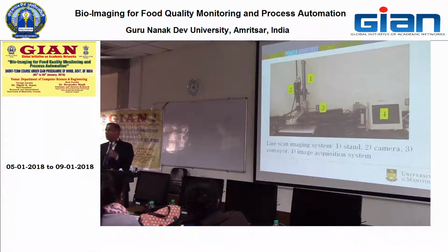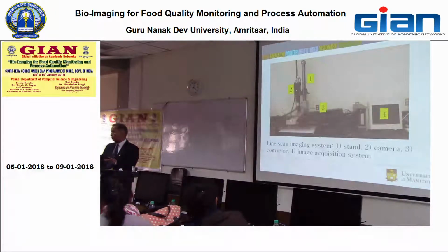By putting the lines together you make your 2-dimensional image and extract the information. You can also use the area scan camera for automation, but you have to design the movement so that there is not too much overlap on the image. Otherwise, you would be confusing the objects. As long as the gap between images is such that they don't overlap, you can use an area scan camera to take pictures of moving objects.